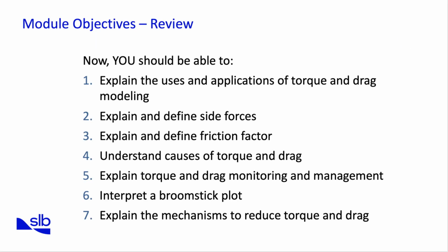We then explained torque and drag monitoring and management, focusing on how pickup and slack-off weights, overpull, and surface torque trends act as diagnostic tools. Finally, we touched on the broomstick plot, a method of graphically comparing measured versus modelled loads to identify abnormal behaviour. We will go into this in more detail later. This concludes submodule 2 of 3.